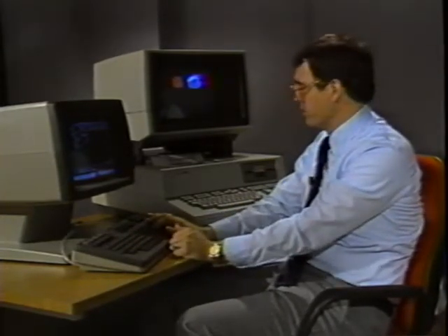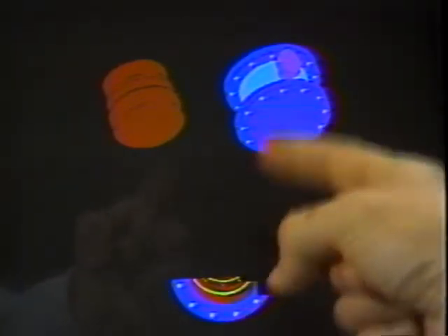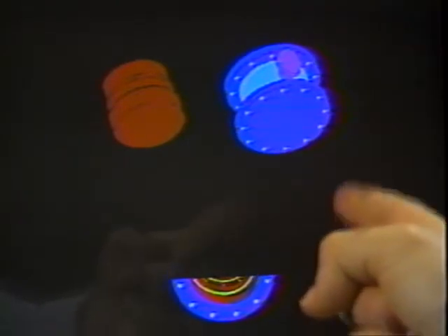Now we perform the subtraction. And as this picture comes in, we should see that the hole is through the central part of the subassembly, and in like manner, I've subtracted out this portion, a central portion in the stem guide, along with a couple of bolt holes that we did just like we did over here.